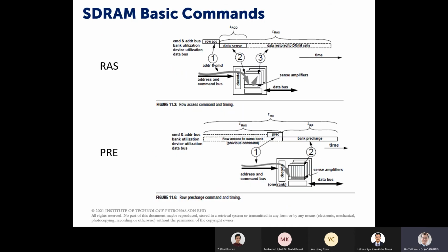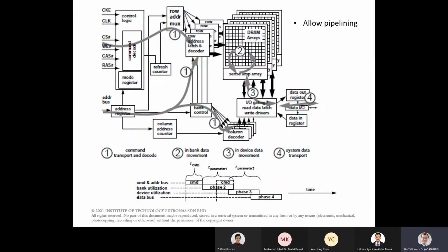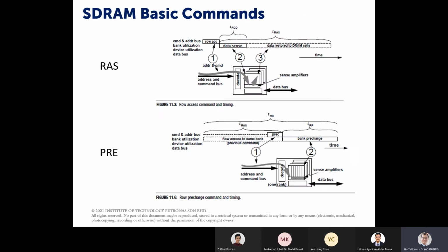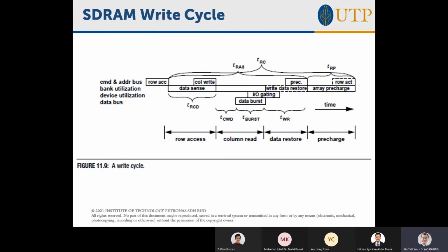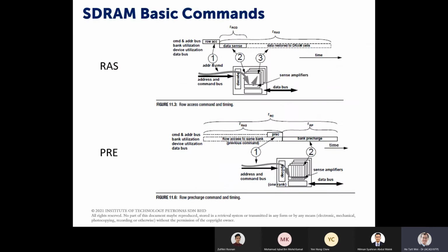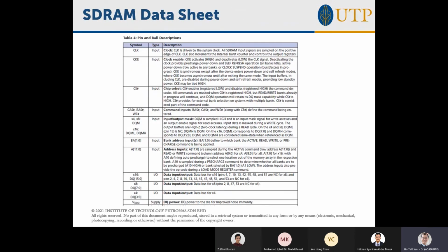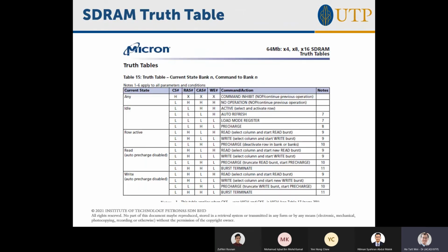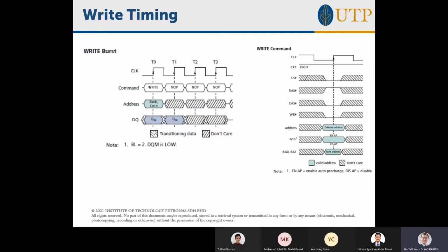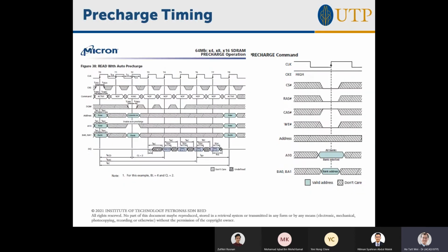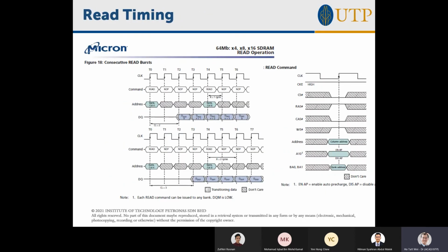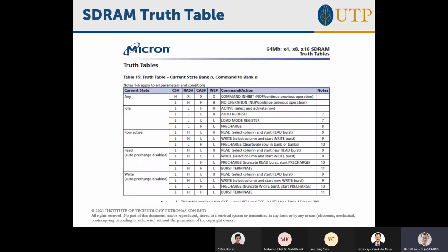All right, so I tell you what, now I'm going to gradually ease you into what's actually going to happen on the chip, how you're going to actually interact with the chip. We're going towards that already. And the timing aspect of things, and then we're going to go into the interface. And then we're going to look at the actual data sheet. How do you actually do this read, write, and pre-charge operation?